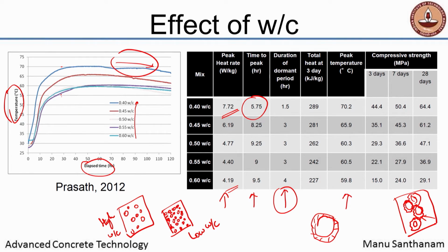A layer of hydrate has been created, because of which it can reduce the penetration of water. Okay, the water has to actually now get through this barrier to react with the cement. So that barrier that forms initially on the cement particle now is preventing the water from reacting with the rest of it. That is the reason for the dormant period. You are forming a hydrate barrier on the cement particles. So water is still freely available to provide you workability, but what happens with time?